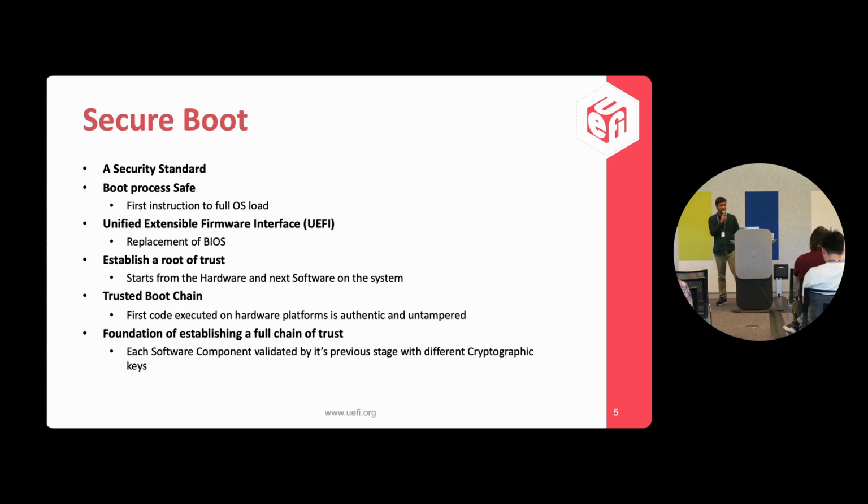So for that we enabled the secure boot feature, and with that we create a complete root of trust with the boot chain mechanism, where many different boot binaries are involved. How the chain of trust works is that each and every binary module gets verified before it gets loaded, with different cryptographic keys.